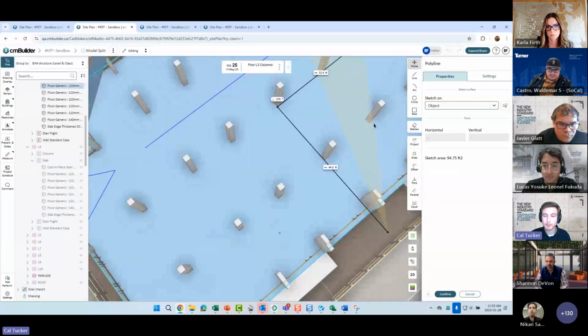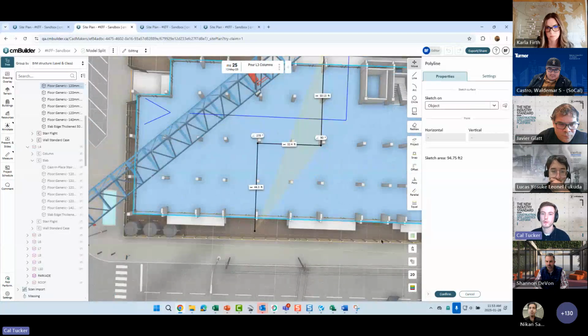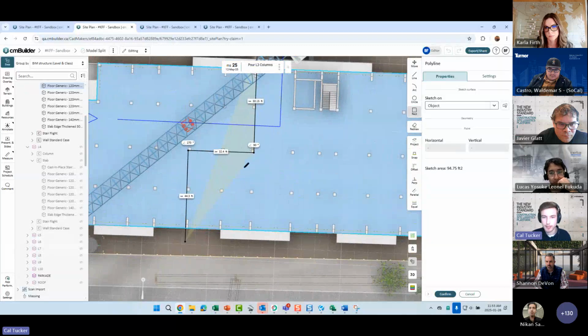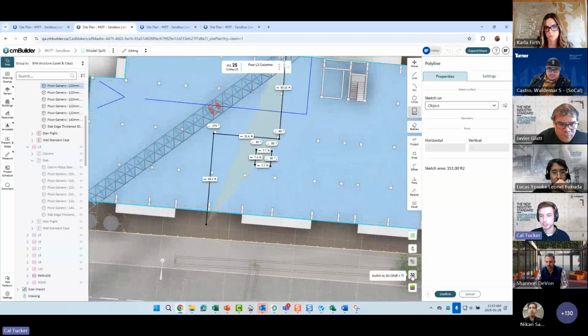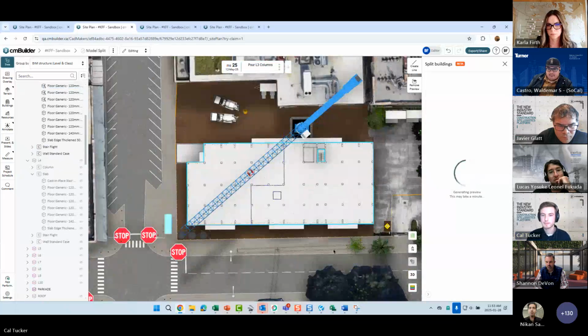And also when we're thinking about our pump truck or our placing boom placement, or maybe a tower crane, a hoist, whatever the case might be, we need to plan for slab openings. So I'm also just going to create a small slab opening, which we will extend our climbing placing boom throughout our construction project. We can select confirm, get a little preview of those slabs, and select confirm there.